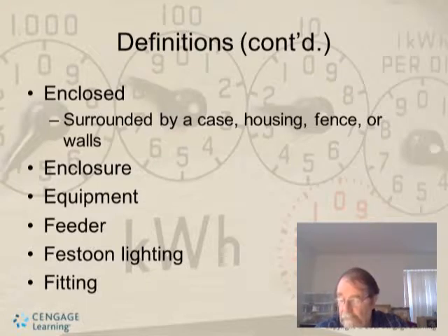in a manner that creates a low impedance circuit facilitating the operation of the overcurrent device or grounding fault detector. It shall be capable of safely carrying the maximum ground fault current likely to be imposed on it from any point on the wiring system where a ground fault may occur to the electrical supply source. The earth shall not be considered as an effective ground fault path.